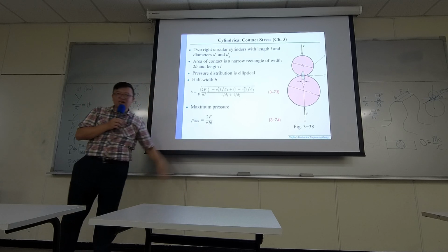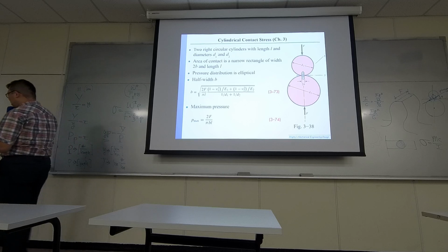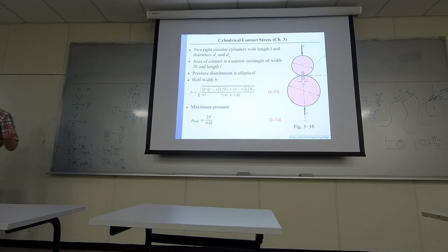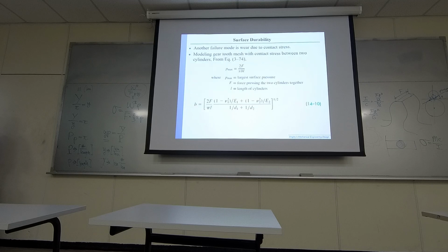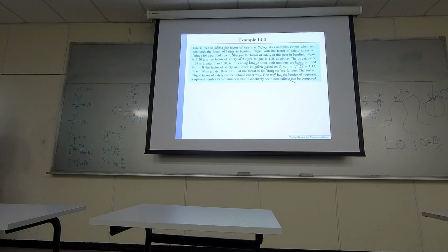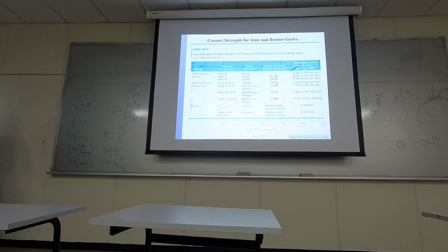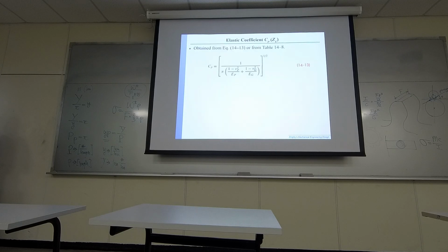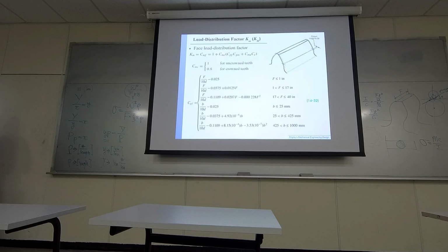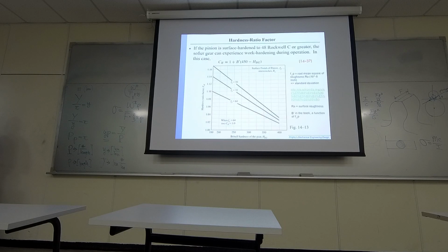And in the entire textbook, actually only gear pairs has this issue. Okay. So there are many different models, and I'm not going to cover them. I just want you to know, if one day you are truly designing gears, you need to know stress is concentrated at the contact surface, and there are already design equations.